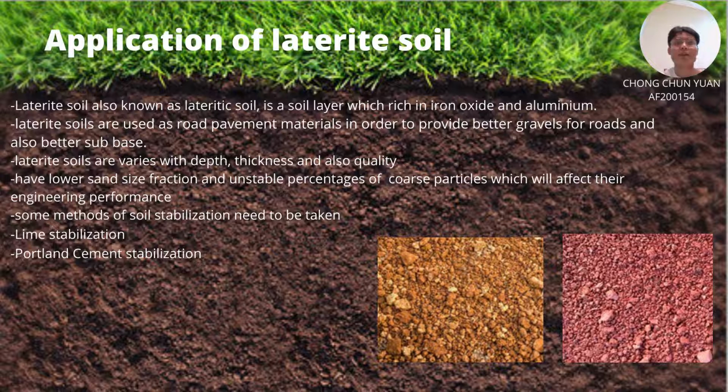Some of the lateritic soil has lower sand size fractions and an unstable percentage of coarse particles, which will affect their engineering performance. Therefore, some methods of soil stabilization need to be taken in order to enhance the soil properties, which are lime stabilization and Portland cement stabilization.